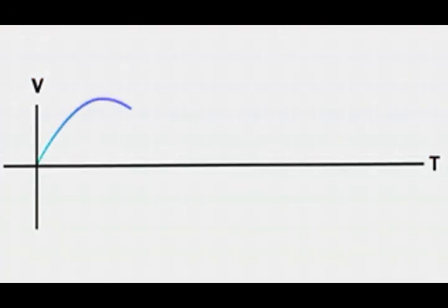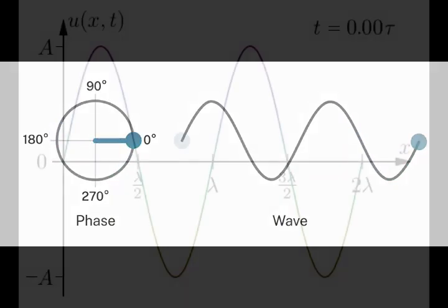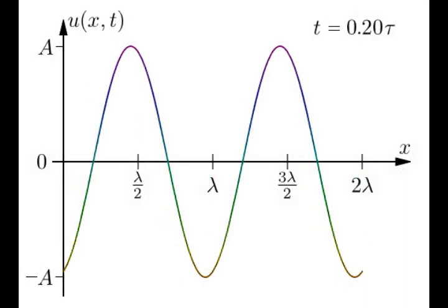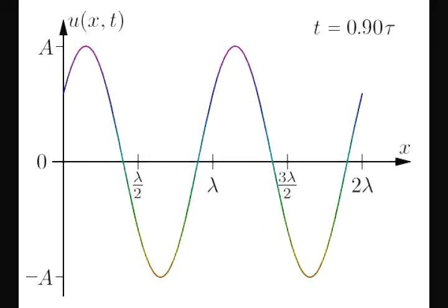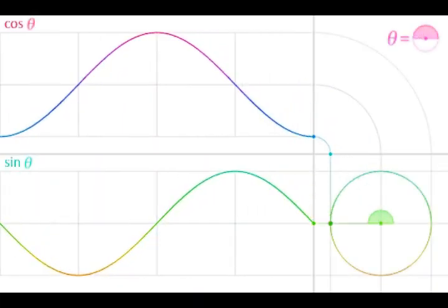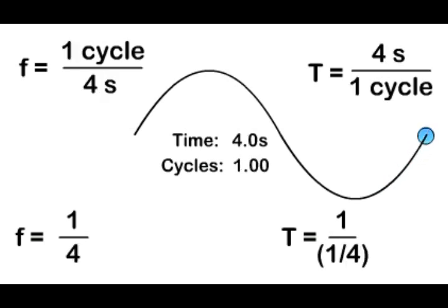A sine wave shape is generally defined by two numbers or parameters. The first number is the degree of rotation of the waveform along the x-axis, which ranges from 0 to 360 degrees. This value is called the period, T, and specifies the interval that the waveform oscillates in one complete cycle. Periodicity is measured in terms of degree and time. The relationship between period and frequency of a sinusoidal waveform is T equals 1 over f.